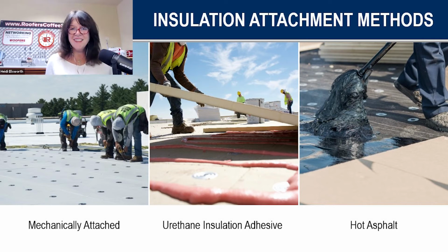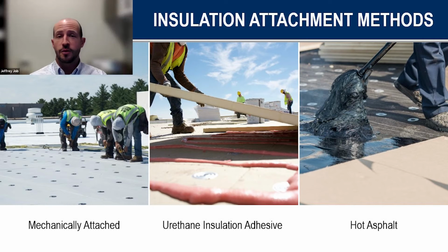Again, you can really do fully fastened all the way through the membrane, laps, etc., or do fully adhered all the way through as well. Fully adhered systems tend to be a little more costly and tend to be higher performance too. So a lot of it is just trade-offs of what the objectives of the project are, the owner, et cetera, and what they're looking for.